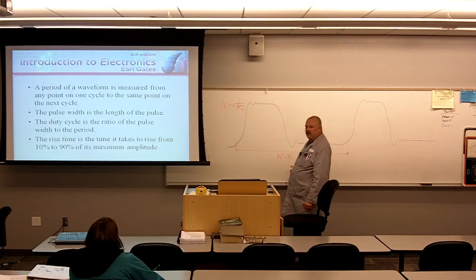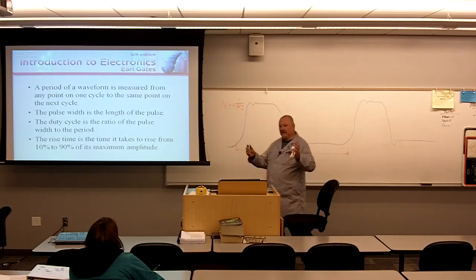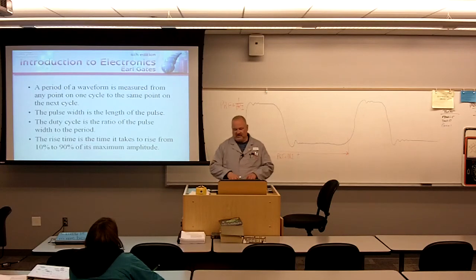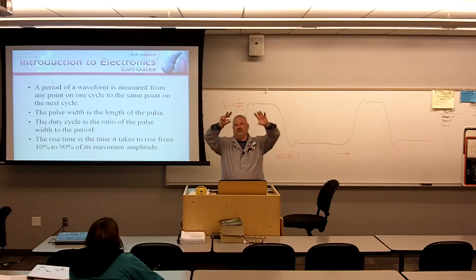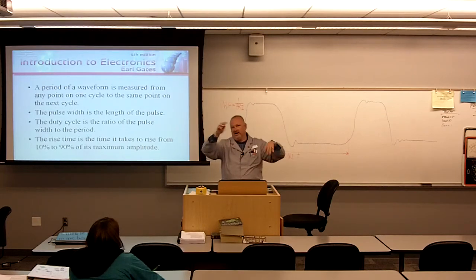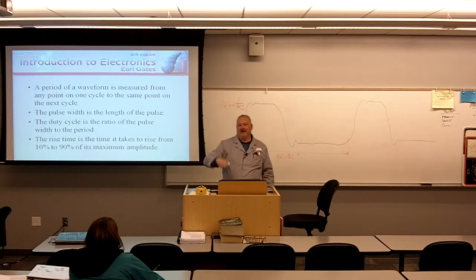Once I figured out what the PRT is, I actually had a calculator. It was in my operator position. I had a computer keyboard in front of me, a screen here, a screen here. There were a couple of oscilloscopes here, spectrum analyzers. But over here on Velcro, we had a calculator. The only reason we had the calculator was I'd plug in the pulse repetition interval and then hit the reciprocal, and that would give me the PRF.